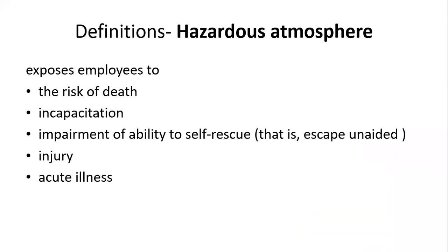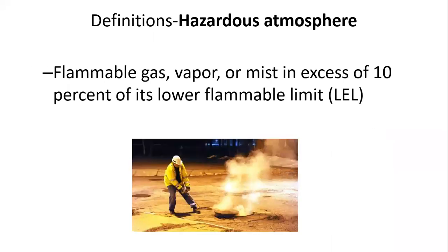Hazardous atmospheres expose employees to death, incapacitation, the impairment to self-rescue. In other words, someone else has to pull you out of there, injury, and of course, acute illness. Hazardous atmospheres: if you have a flammable gas, it can be hazardous, and it's probably above the lower flammable limit. By the way, we also call that the LEL, the lower explosive limit.